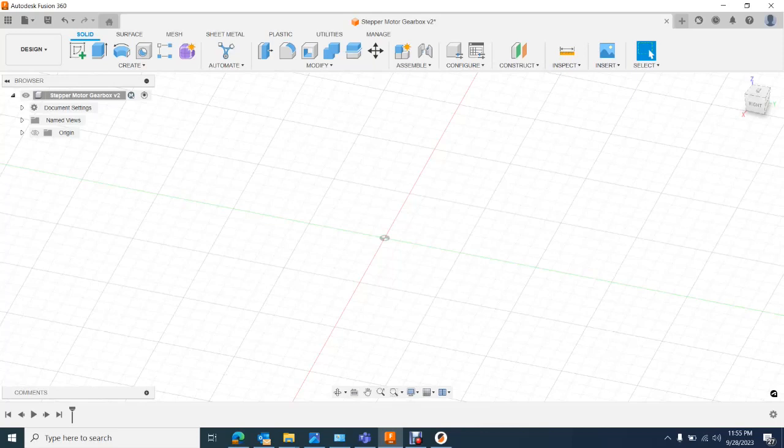Upon looking at other projects on YouTube, I noticed a lot of sturdier robots that were achieving precision of 0.2 millimeters or better using stepper motors. So I went ahead and bought some NEMA 23 stepper motors. The problem was, though, that when they came in, they were a little bit bigger than what I want my robot to be.